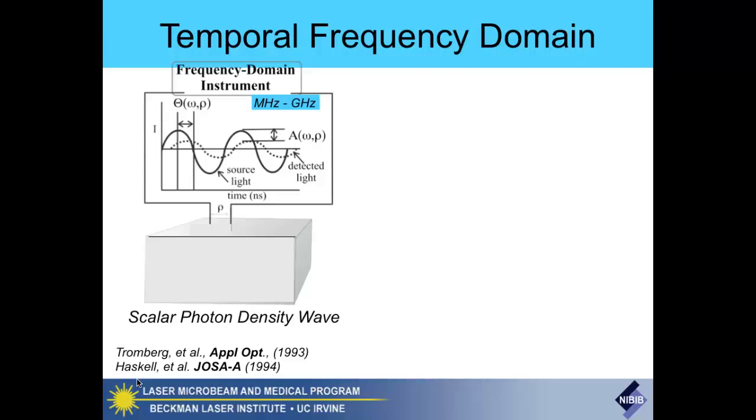What if you're not at that threshold level? You basically have an LED, a very expensive LED. Well, probably not very expensive; it's not as expensive as it used to be. The difference between the LED and the LD is that you've got a cavity structure that's conducive to lasing, and you've given just enough current to get above threshold for that lasing process to occur.